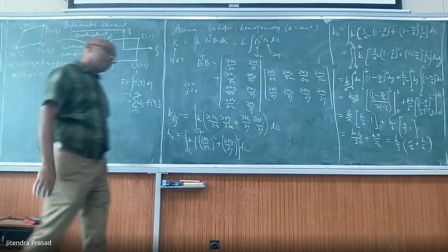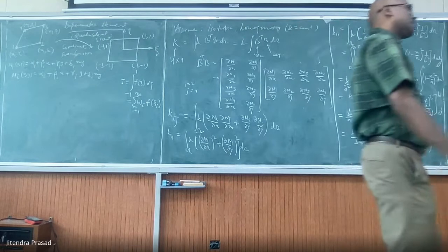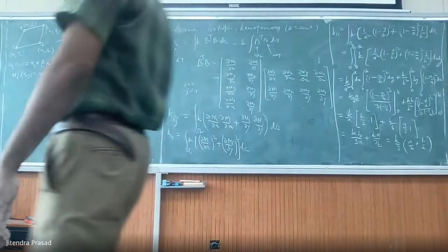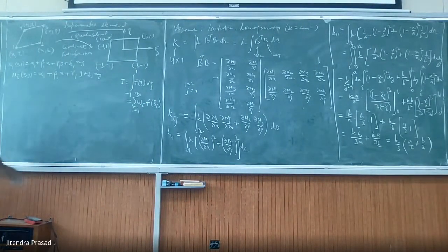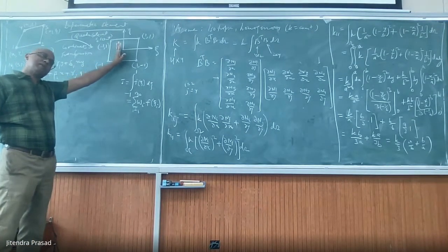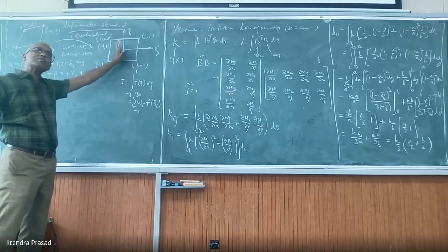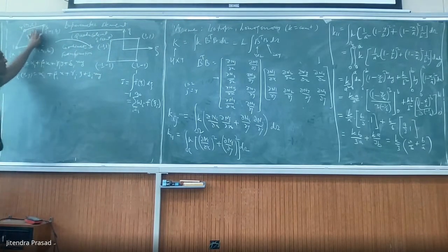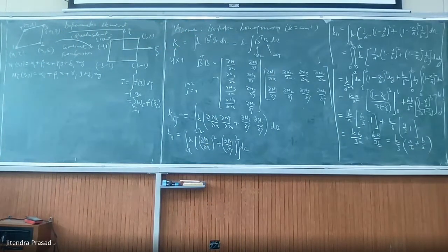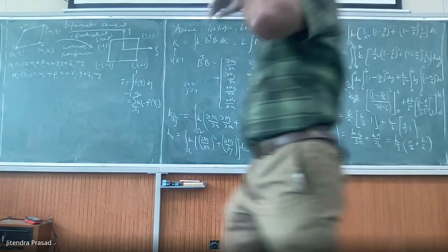Remember that you are working with finite element analysis of aircraft or ships, which may have lakhs, if not millions, of elements, right? In that case you will face a problem, because if you save a little bit of time, that accumulates and becomes a big time, right? So that's why the isoparametric element helps in that way. You formulate that way. In the computer, it doesn't even know what you are doing. You choose this or automatically transform this, because the derivation becomes easier. So that's fine. Any questions, guys?